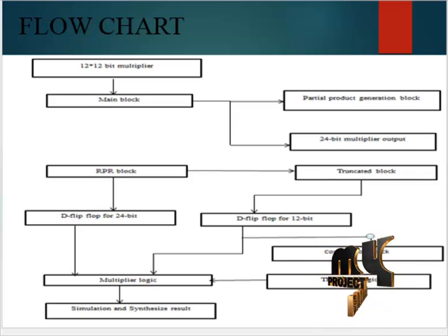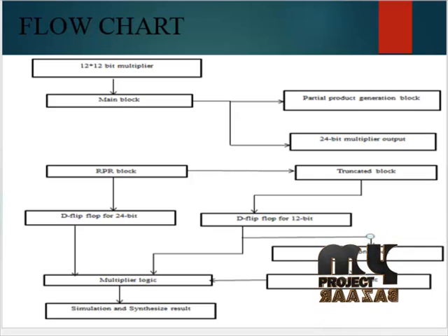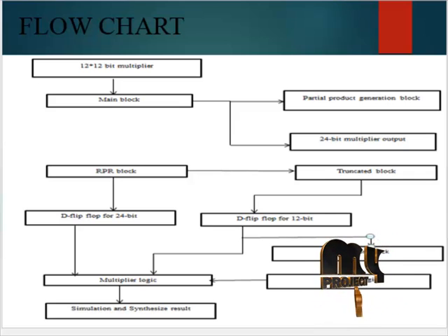These adders require a small area and low power, with a short critical delay. The 2-bit adder implementation of the recoding adder handles the generation of triple multiples with no carry propagation. After that we go into the OR blocks.